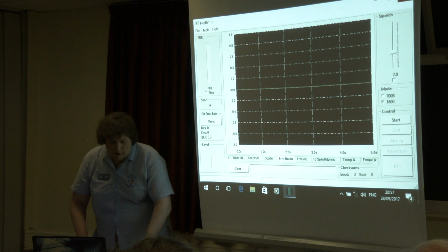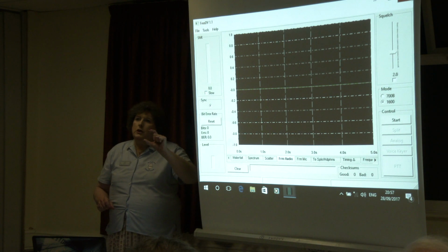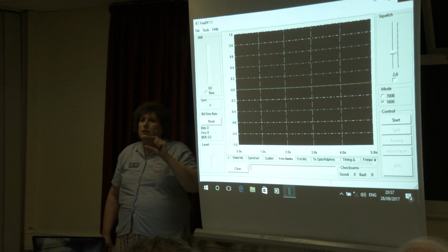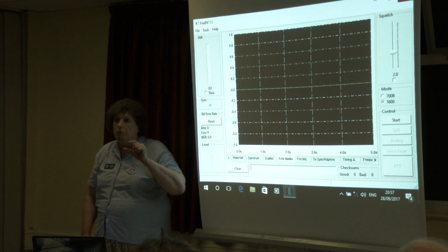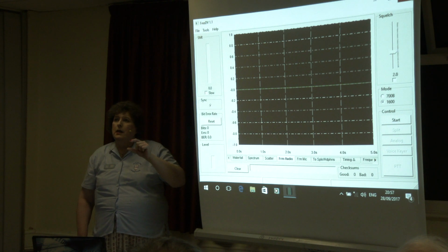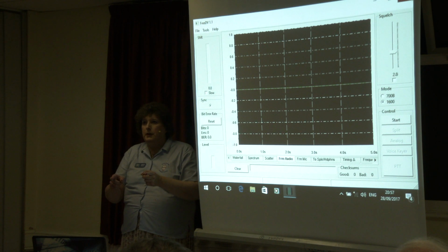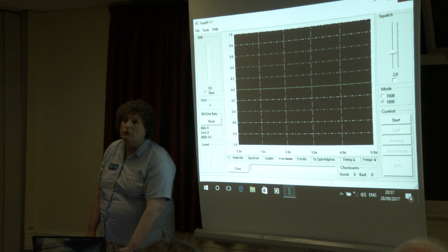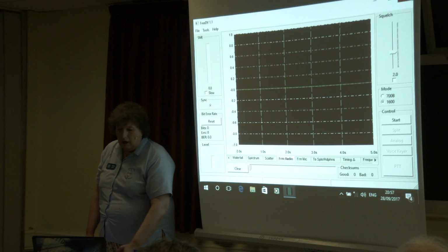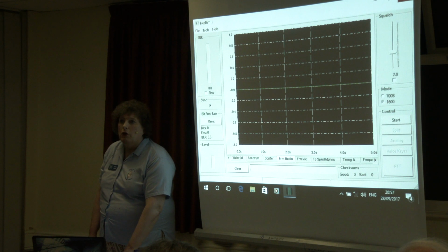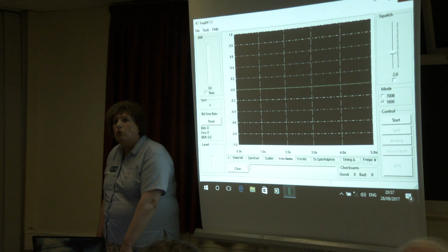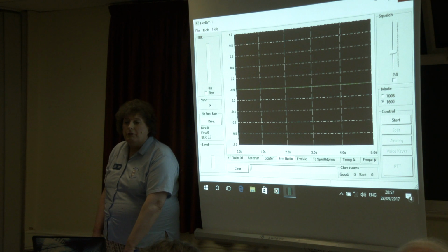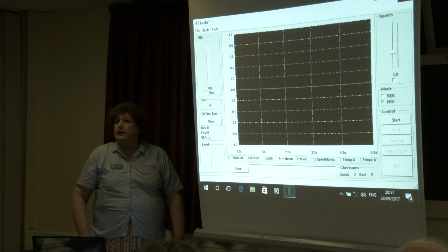Yeah. I mean, where I usually plug into my PCs is little USB external audio adapters. Now I prefer to use the USB audio adapters mainly because they're isolated as far as the radio is concerned from the PC. It also means the sound quality and signal to noise ratio is much better, whereas if you use the audio that's on board in the PC, it tends to contain a fair bit of mush from the digital noises of the PC itself.